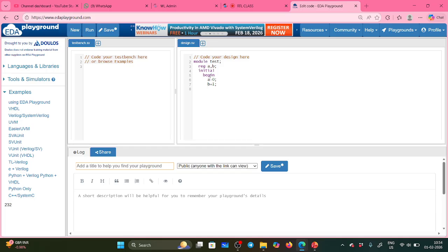I want to display: $display the value of a is %d, and b is %d, a comma b. Okay, a comma b, and I'm introducing one delay.